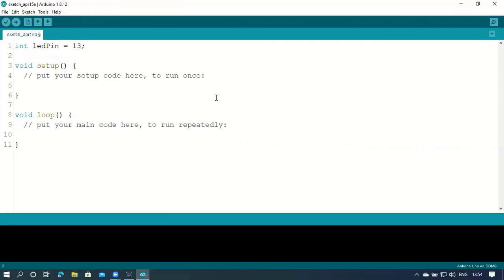All right, so for now we are done with declaring our variable, and because the microcontroller has general purpose input output pins, we'll have to specify to the microcontroller that we are actually using pin 13 as an input pin or an output pin. How do we do that? The decision is dependent on the type of component you are connecting to the microcontroller. This time, we are connecting an LED.